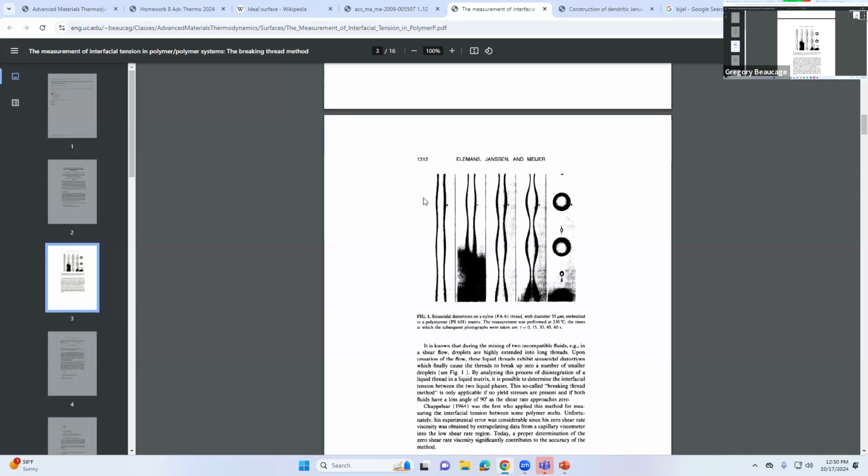And then he sticks that into an optical micrograph, and the thread wants to decay into blobs, just a normal surface area reduction. So it's got a high surface area with the fiber and it wants to become spheres. The process of it turning into spheres involves this oscillating feature that shows up. And then the amplitude of that oscillation, so it starts with A0, and then this is A. So A is going to be larger than A0, and it'll gradually grow into a sphere over time.